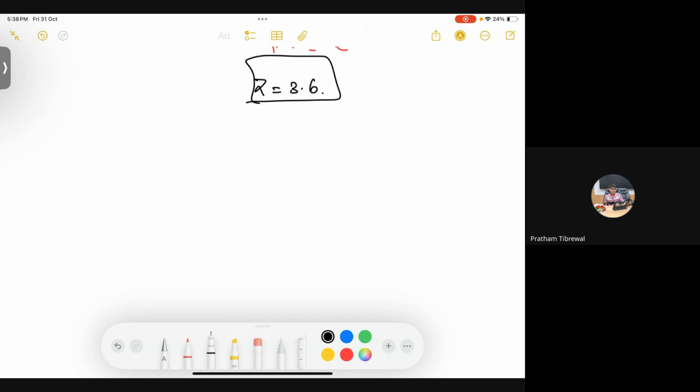Can you now find the velocity error constant of the system after adding this zero? Kv, where z is equal to minus 3.6. The zero has been added at s plus 3.6.